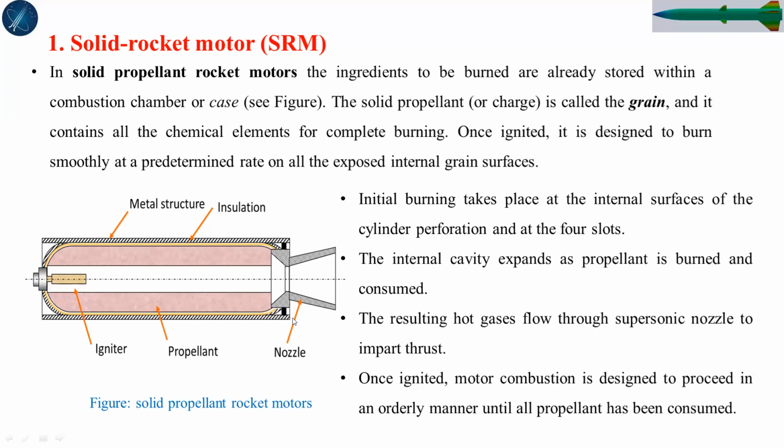Try to design; first select an appropriate propellant. We have solid propellant of this shape, cylindrical shape with internal perforation. So there is a cylindrical hollow internal surface, or it can be star shape, depending upon our requirement.